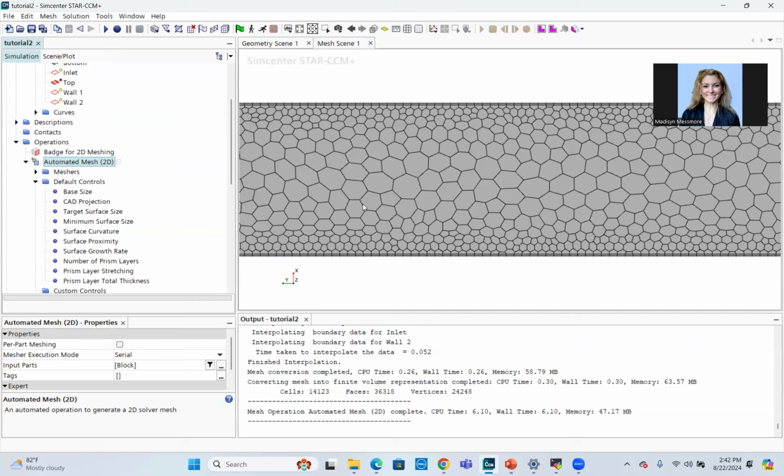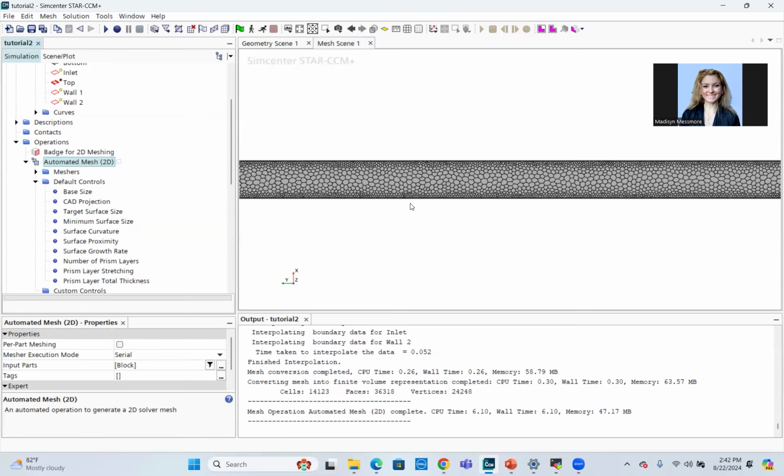And in our case, we're not doing anything crazy, so I think this should probably be fine. There's ways that you can be really good. You're supposed to do a grid refinement study where you effectively run your simulation with one mesh size, decrease your mesh size by half. There's different methods, but the one I usually do is you decrease the chunk size by half, run it again and then compare your results.